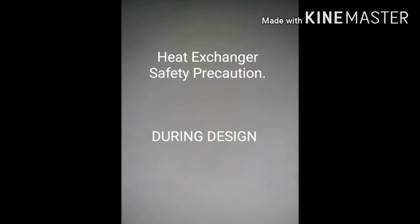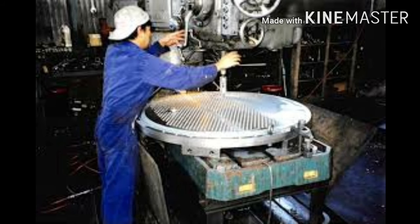Okay, so it is very important that this is some heat exchanger safety precaution during design. 1. Make sure you have decided the appropriate design condition for the heat exchanger type, temperature design, pressure design, material compatibility, supports, gas vent, drain, and structural design. Inappropriate design will lead to mechanical integrity problems. 2. Pay attention to the gasket material. Material selection and thickness have to be matched to avoid leakage.